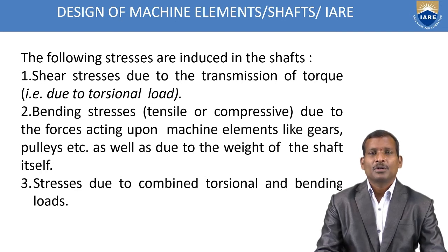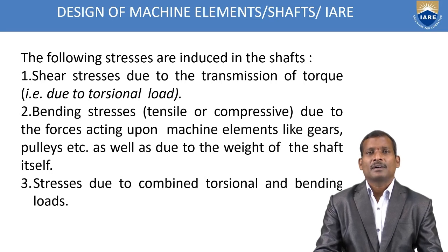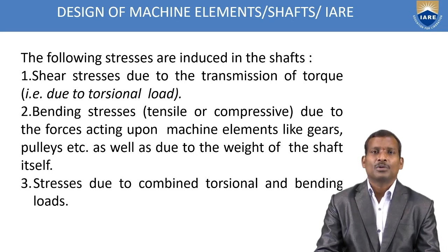Already you know the torsion loads and bending loads, and the combination of these two loads, and axial loads also will act on a shaft. While designing a shaft, all these values you should calculate. Then only you will get a good design.